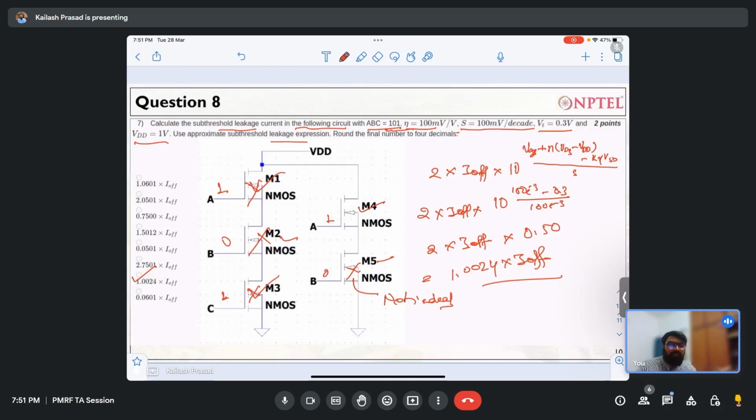So whenever you design hardware for a device like a smartwatch, a pacemaker, or handheld devices which are not running at very high frequency, not at 1 gigahertz or 2 gigahertz like your laptop, what do you want? There you use transistors which are extremely low leakage, though they can be of subpar performance. You don't want 1 gigahertz frequency. If it is giving you 100 megahertz, it is fine. If it is giving 150 megahertz, it is fine. And there you use high threshold voltage transistors, HVT transistors.